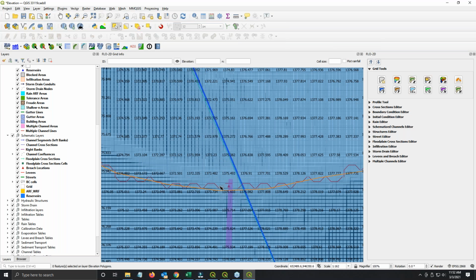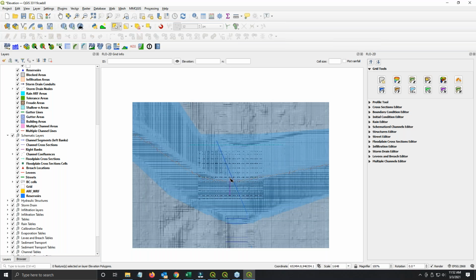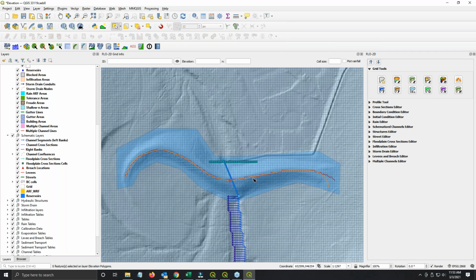And don't ignore this, this is a mistake that I made. But you can see your failure point right here, and it will fail the levee, and the levee failure will spread in both directions. And the elevation of the dam is extracted from the grid using the boundary of the polygon to reset the elevation to take the dam out. So that's an important method, and I'm sorry I spent so much time on that, but it's an important method for people who are running dam breach and levee breach.